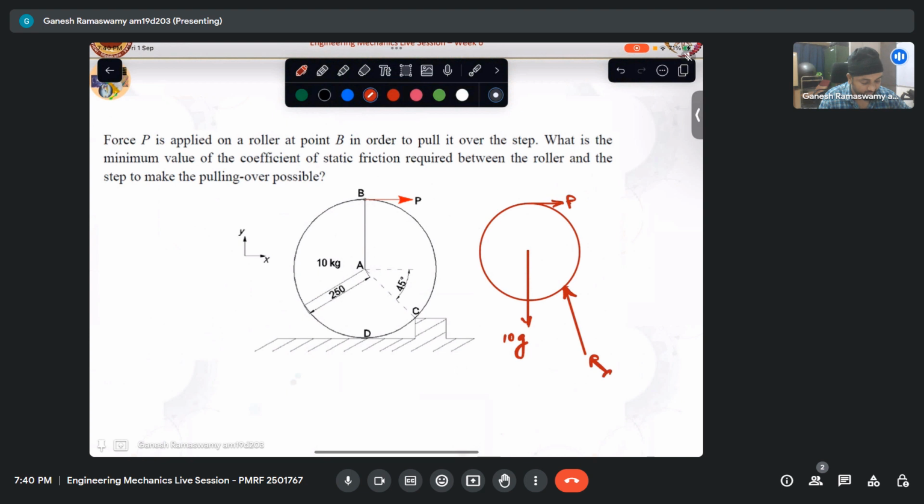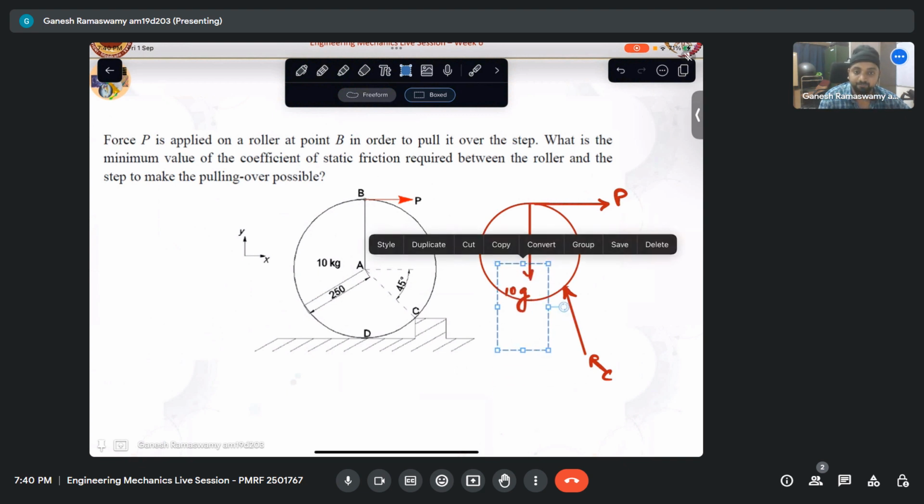And then I have force P applied. Let me pull that out a little more like that. This is P. Now this is a three force system. That is a body with three forces. In such a case, from principle of transmissibility, I can take this force, move it along its line of action and bring it here. That is very much possible without changing the external effects.